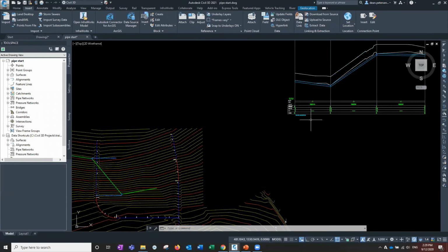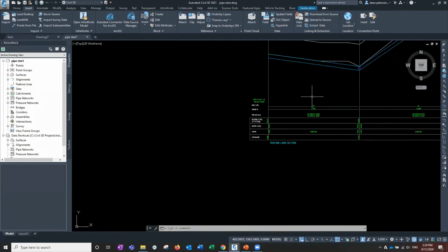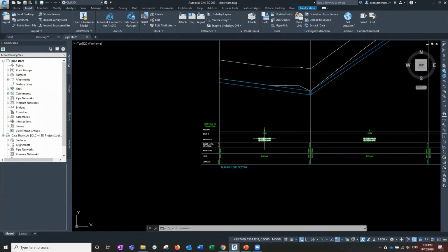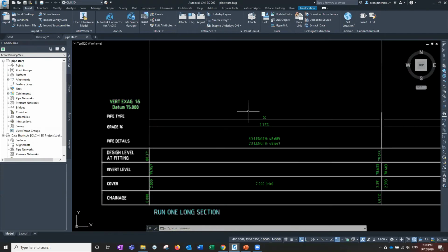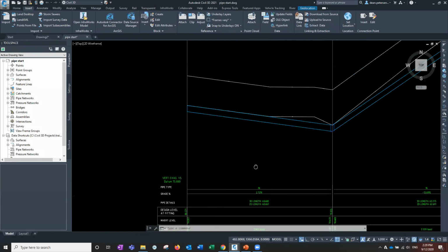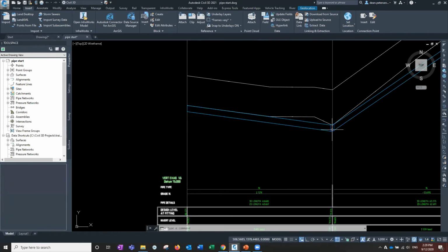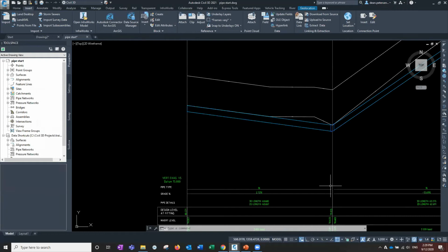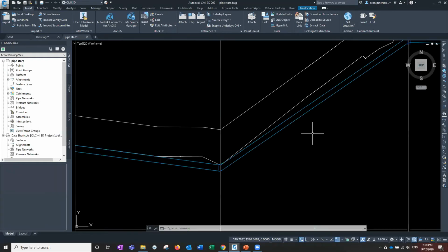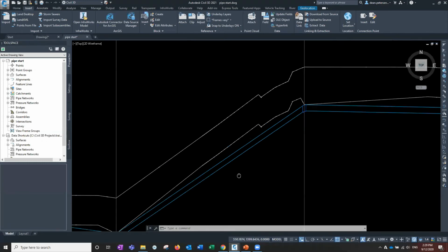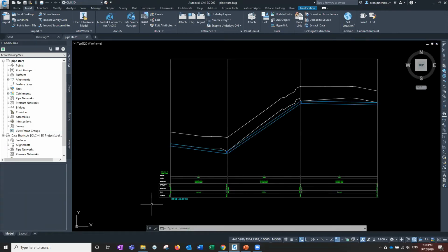In these bands, I have a request out with Autodesk at the moment. The band information, such as the pipe type, so getting the type of that pipe or its size down in the bands, isn't working at the moment. Likewise, the fitting sizes down into the bands are also not functional at the moment, although you could put a label up in here next to the actual objects which can access that data, but that just won't go into the bands at the moment.